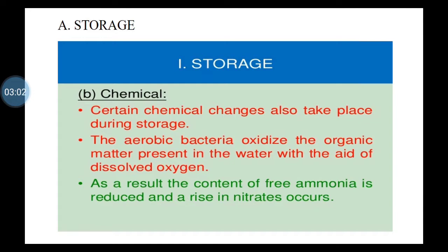Then certain chemical changes also take place when we store water for 24 or 48 hours. So physical changes take place, and chemical changes. What chemical changes will take place? Whatever harmful germs are present are destroyed naturally, and microorganisms decrease. Then the aerobic bacteria oxidize the organic matter present in water with the aid of dissolved oxygen, and as a result, the content of free ammonia is reduced and nitrates are increased.